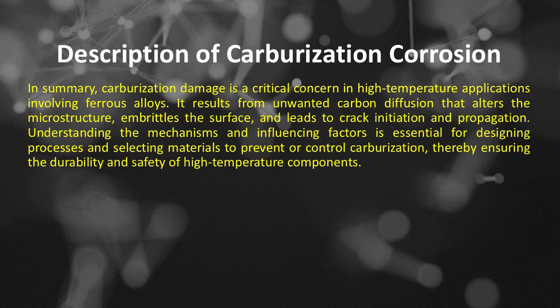In summary, carburization damage is a critical concern in high-temperature applications involving ferrous alloys. It results from unwanted carbon diffusion that alters the microstructure, embrittles the surface, and leads to crack initiation and propagation. Understanding the mechanisms and influencing factors is essential for designing processes and selecting materials to prevent or control carburization, thereby ensuring the durability and safety of high-temperature components.